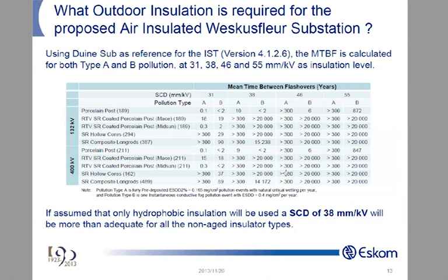And as they migrate into the pollution layer, is this bottom part in the layer dissolvable? No. But the area at the top is becoming smaller, smaller, smaller because they're migrating up. So what's happening to the area A? Becoming smaller, smaller, smaller. R goes up, up, up. The resistivity of that whole layer goes up, up, up. R goes up, up, up. I becomes small. Your risk of flashover far lower. You got it? Cool. You've been empowered.